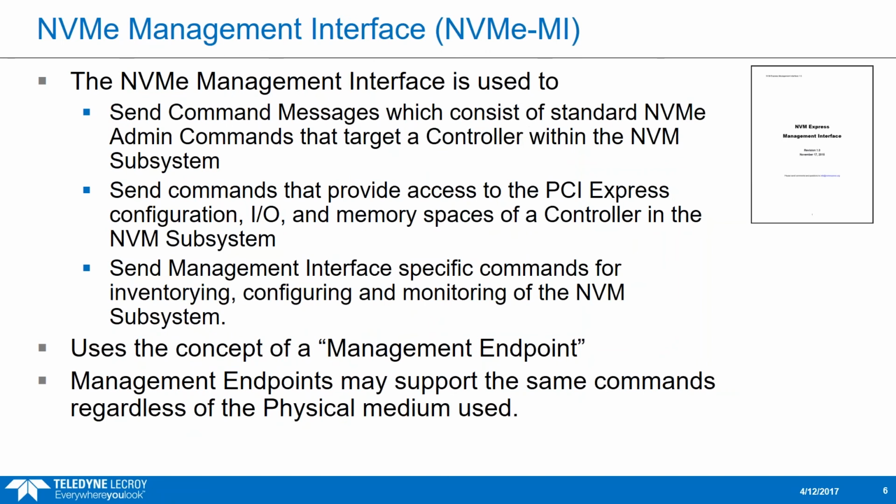So what I've tried to do in the presentation here is I note on the side which specification this is referring to, and a lot of this is taken, interpreted from the specification. So the NVMe Management Interface is used to send command messages which consist of standard NVMe admin commands that target a controller within the NVM subsystem. It can also be used to send commands that provide access to the PCI Express configuration space, I/O space, and memory space of a controller in the NVM subsystem, and also to send specific management interface commands that can be used for inventory or configuring or monitoring in the NVM subsystem.